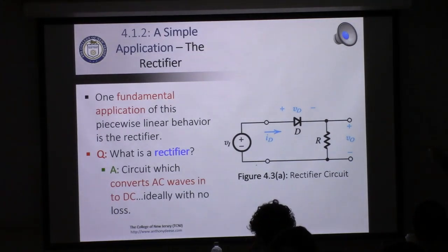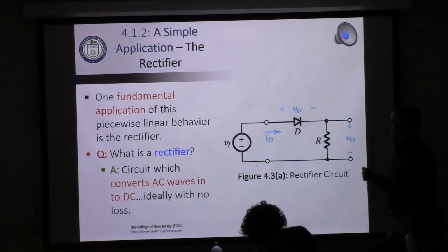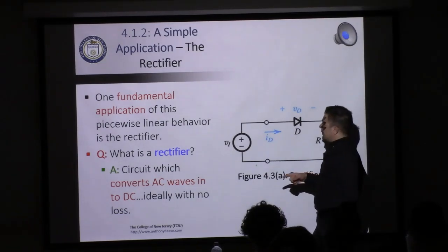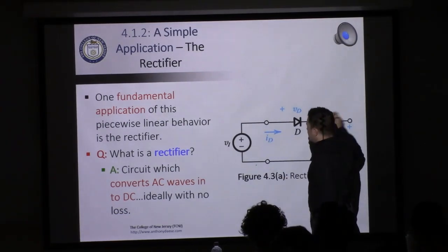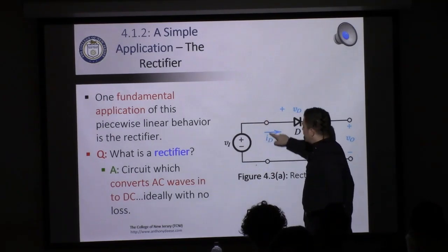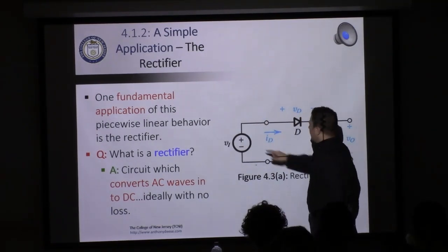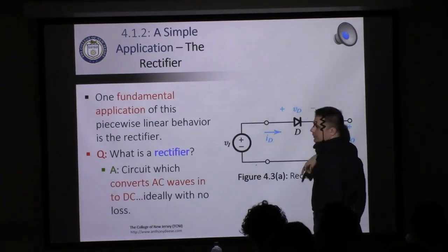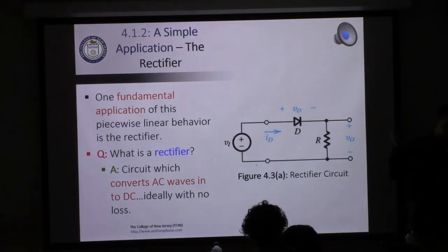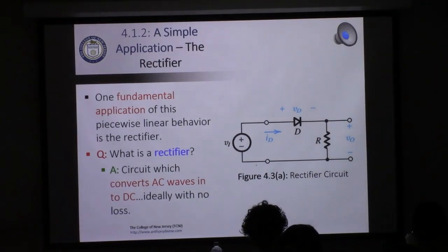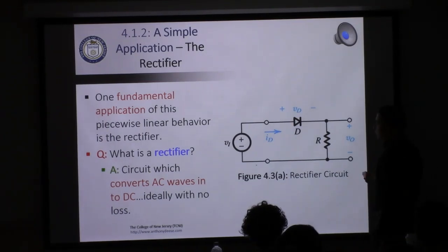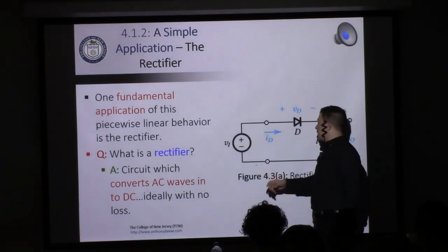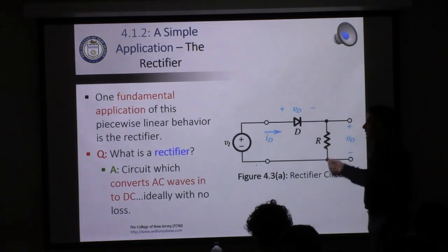And this is a half-wave rectifier. And what that means is it takes our AC waveform, and instead of flipping the bottom up, it only gives us half the wave. So it'll be signal, no signal, signal, no signal. A basic half-wave diode rectifier can be built just using a single diode as shown here. So this would be an AC source, this is your ideal diode, and this is your load.